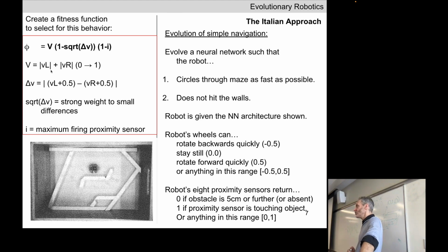Whatever the robot should do, it should always be spinning its wheels. Yeah? Okay. However, that's not going to be sufficient for our purposes, right? Because as we've seen, one perverse instantiation of just V would be spin the left wheel forward and spin the right wheel backwards. So maximizing V alone, one way to do that is for the robot to turn in place.